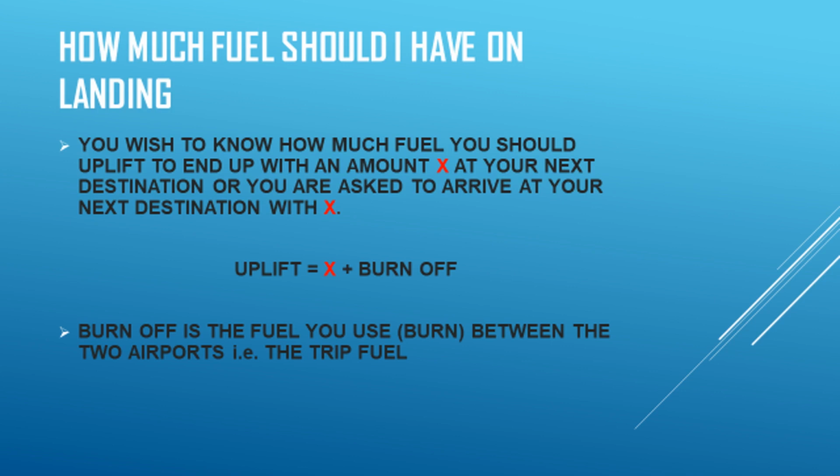You are at airport B, which is your departure point. In simple terms, you just have to know how much you will burn between B and C, okay? And then you add to this the amount that you want to land with at your base, which is X, and all this tells you how much you should put in your tanks, which is called the uplift.